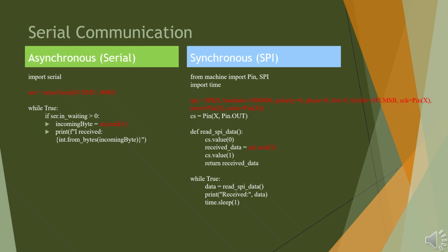This is especially useful when you want to send commands to a microcontroller, log sensor data, or build a GUI that interacts with embedded systems in real time. In the example shown, the program continuously checks for incoming data and prints it to the terminal, making it a simple UART monitor. On the other hand, MicroPython runs directly on embedded devices like the Raspberry Pi Pico, RP2040, ESP32, or similar boards. It provides hardware-level access to communication interfaces through the machine module.